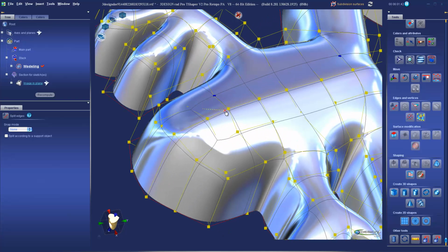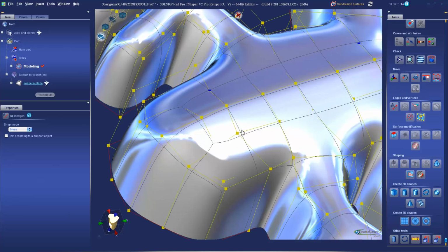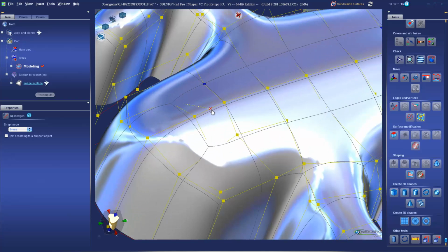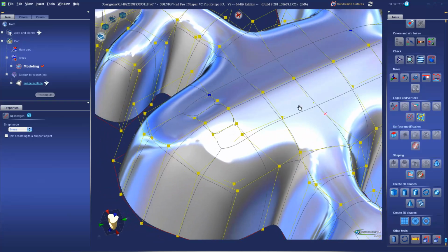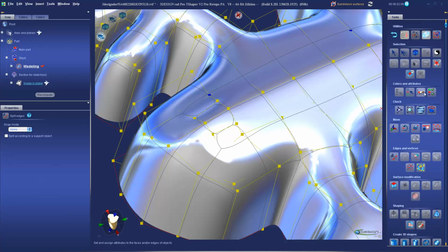So this section here for each side of the eyes means I'm going to have to divide that up a little bit too, because I don't want his eyes to be touching in the center. So spacebar again and split across this direction. That's for one eye, and then split across this one. Now when we've done those splits, we've essentially created some n-gons around it, which is not going to give us the smoothest model. We may have to clean some of that up. Let's see how it looks after we do our extrusions.